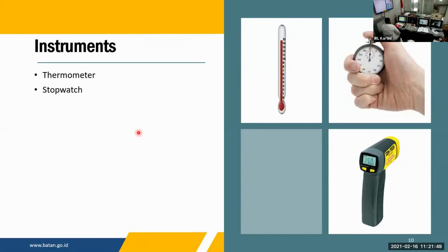We also need to have a stopwatch or a clock, because we need to have a good consistency in when we take the time. So typically we take the data every 5 minutes. If you take the data not consistently, so for example, one is taken in the interval of 4 minutes, and then you take it after 5 minutes, and then you take it after 6 minutes, even though in 15 minutes you have 3 sets of data and it averages at 5 minutes, because the data is not taken consistently, there may be some inconsistencies in your calculation. So it will be better if you have a stopwatch, or you have your cell phone, you have a timer, and you can put the alarm or something, so that you can take the data at regular intervals with accurate intervals between data taking.